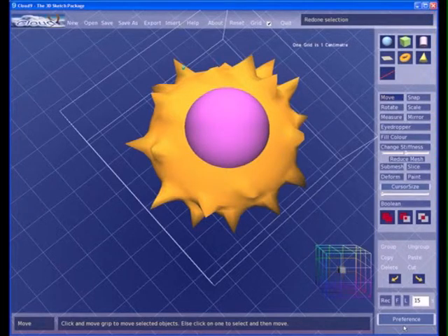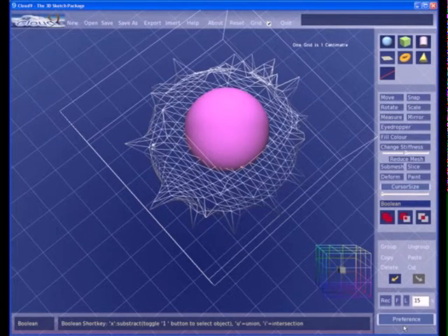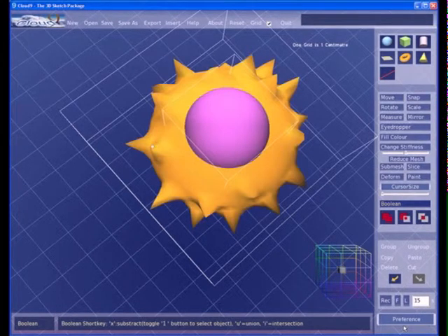Then I've selected both objects, so now I select the pink one, so that's holding down Shift plus the back button on the Falcon. Then go to the boolean bar, click on that. Now I want this pink object removed from the yellow one, so toggle the one key on your keyboard, and you can see that's the yellow one, so I don't want that one selected, I want the pink one, which is that one. Then you can click on the middle icon and it'll perform the Boolean operation.